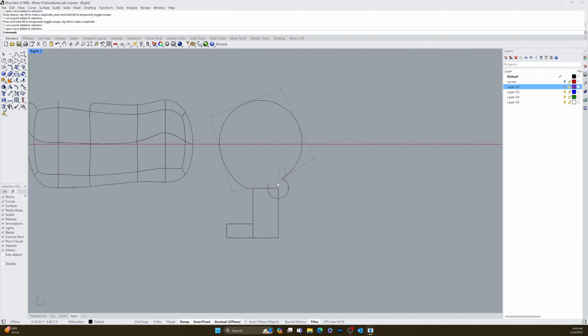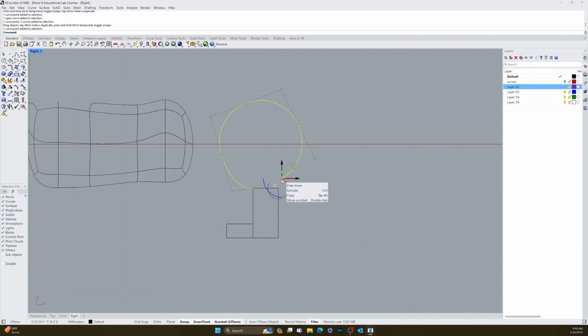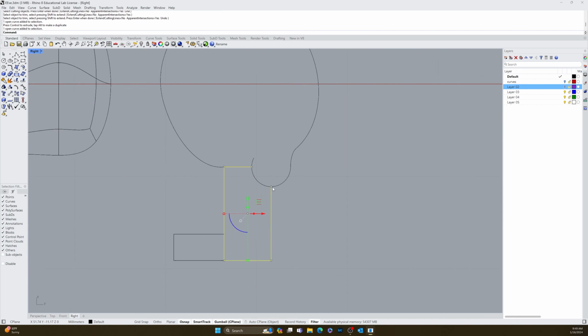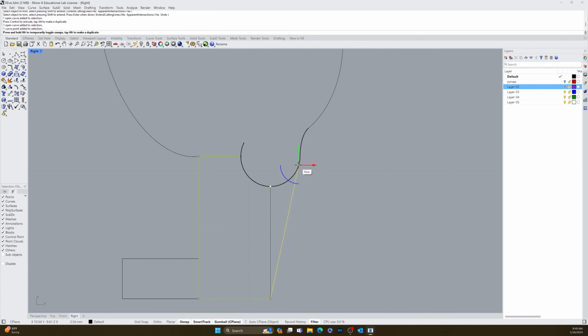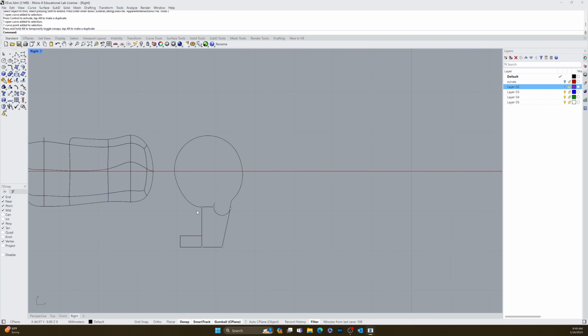So click on both of these objects. And there's a point that they have in common. Click on it. Curve point, shift, click on it to grab the other curve point. There we go. And then I'll just do a trim using this. And then I'm going to grab this edge. Whoops. Don't want the whole thing. Grab that point and move it there. And under my snaps here, I've got the near on, which helps with some of this stuff.